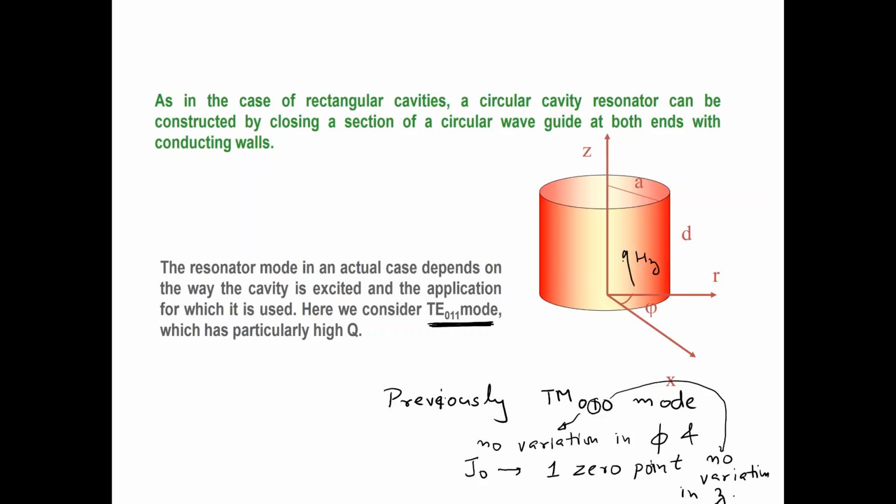because this HZ component is present and is hitting perpendicularly across the region, HZ would be a sine formation, and so it will have to have some variation along the Z direction too. Otherwise, you basically have 0 here and 0 there, and if everywhere it is 0, then you don't have any mode present. So you have one half wavelength which would fit within the Z direction also.